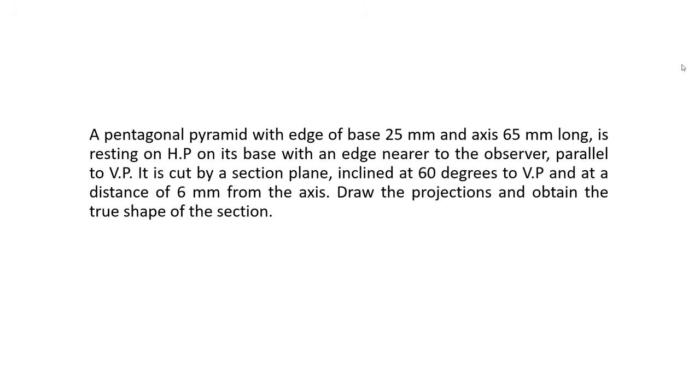In this video we will see a question based on section of solids, section of a pentagonal pyramid when the section plane is perpendicular to the horizontal plane and inclined to the vertical plane.